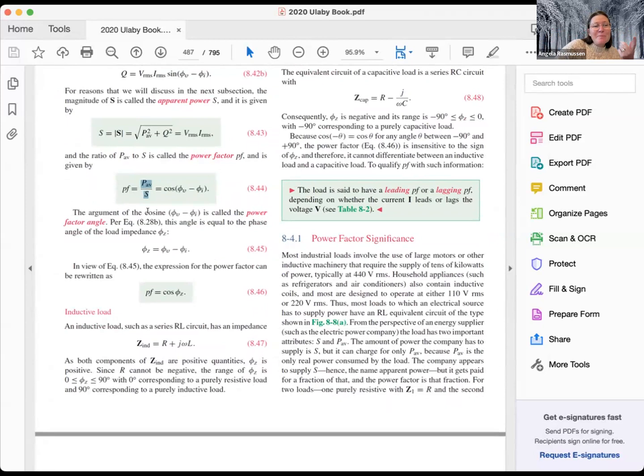So the power factor is what we take away from the complex power, but we want to understand the terms, because when you take a power course or even talk about power systems, they will have these terms in there. The reactive power is just a value, it doesn't mean anything per se, but the power factor itself will tell you whether it has more real components and characteristics, or acts more like a system that has capacitors and inductors in it.